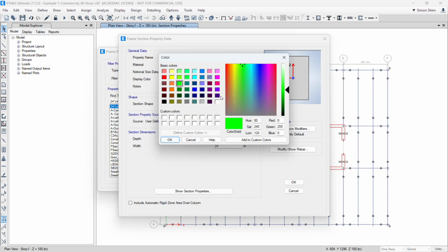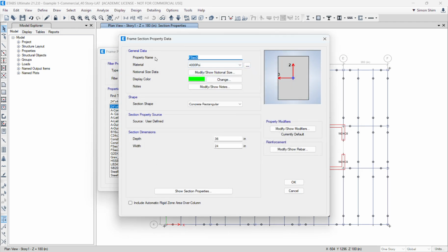So in order to do that, I'm gonna create the link beam concrete beam by clicking here, add a new property, right? In this case I'll call it our link beam, right? The width usually matches the wall thickness, so 24 inches. The depth varies, but I'll keep it at 24 inches deep. For the concrete strength of the 24-inch wall, I chose 9,000, so I'm gonna match the concrete strength as well. When they pour the concrete wall, they're gonna pour the link beam as well. So we always match the concrete strength, right? So 24, 24, C9, C9.